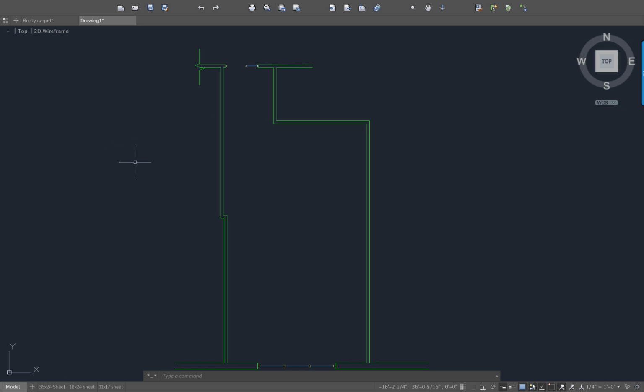Okay. To draw a break line, one thing is that you can specify the size, and here's where life gets a little more complicated. I'll type S for size. The size of the break line is the printed size, not the drawing size. So just be aware of that as you draw it.